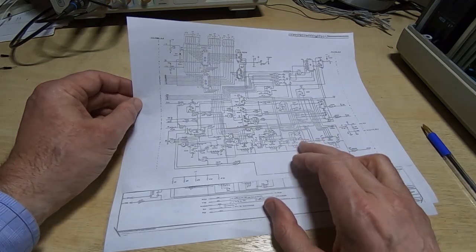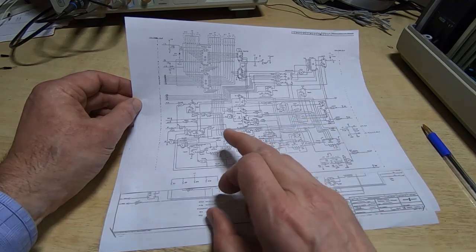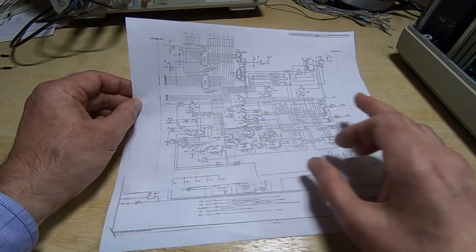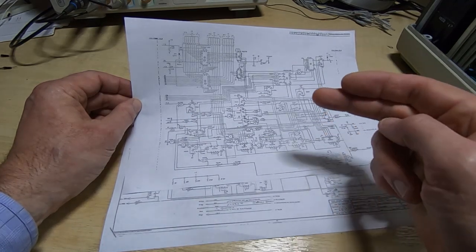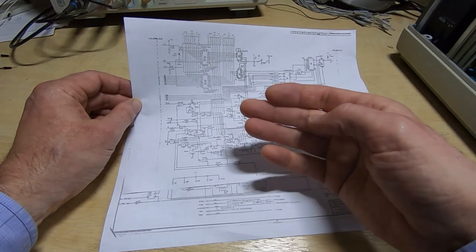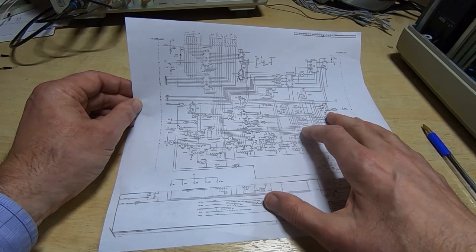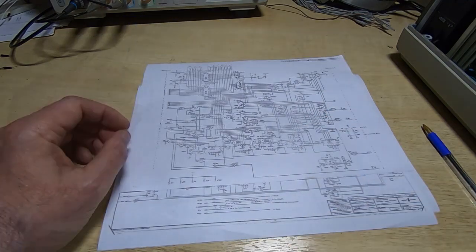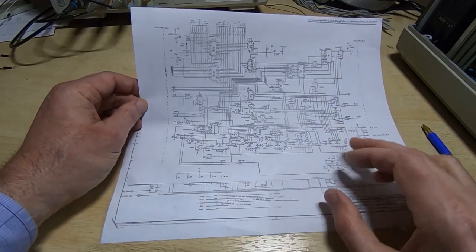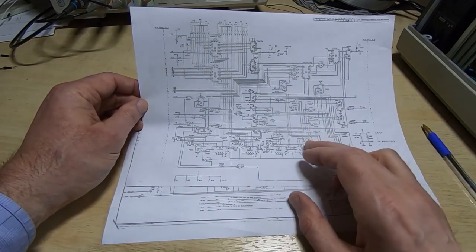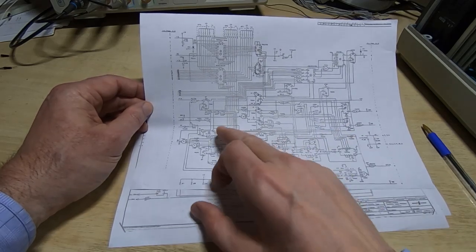Most systems that employ scanning CRT displays will go through every single memory location every scan and essentially transfer the information that's in the RAM onto the screen. This doesn't necessarily do that, and understanding the way this operates will make more sense hopefully as we go through this video, and also explain why I don't believe it's just a simple counter fault in this case.